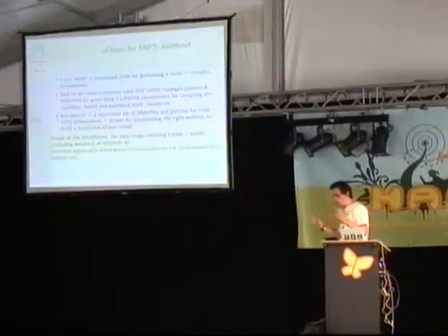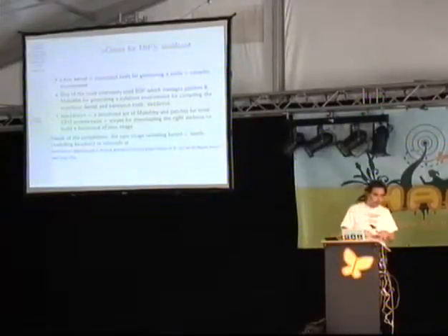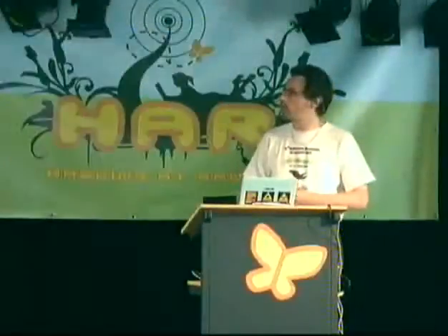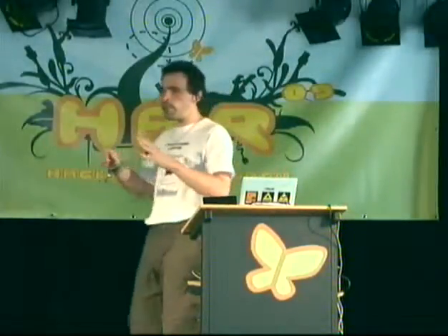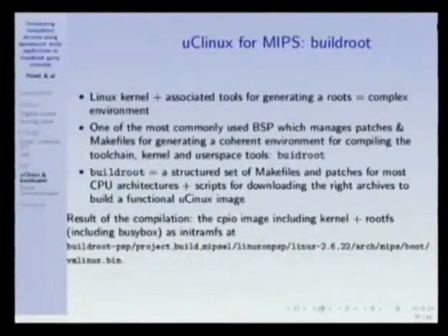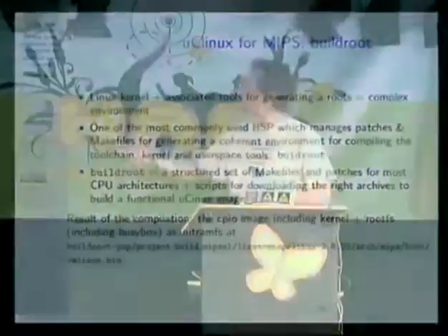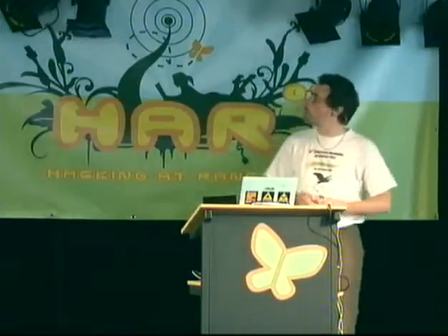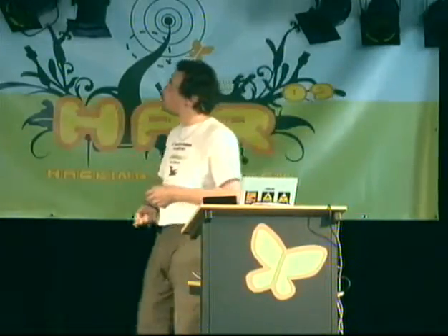Buildroot is simply a set of makefiles and a set of tools for helping you generate your board support package. And most important, it will generate the tool chain for compiling both the kernel and the applications, which means that necessarily these two pieces of software will be coherent. They will pass arguments in the right way. And so our main contribution in this work was generating a buildroot environment compatible with the MMU-less MIPS as used in the PSP. And at the end of the day, what you get is Linux running on a PlayStation Portable